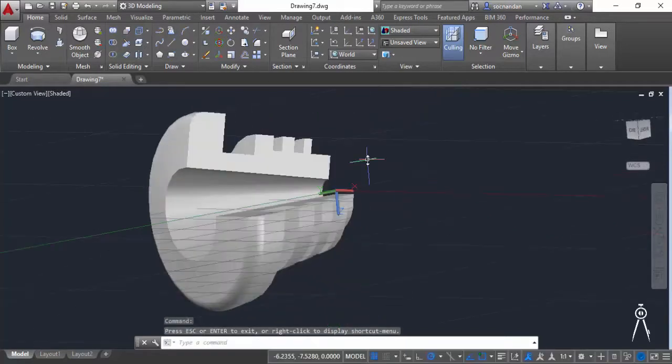Let's orbit it. In this way you can use different kinds of geometries for making a revolved 3D shape, and for that you can use other geometries like arc or spline as well. But the condition is that the geometry needs to be completely closed. In the next section, I will tell you about the Sweep command of AutoCAD.